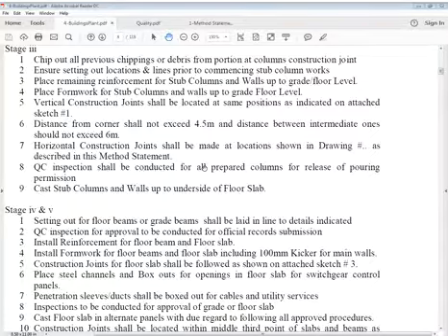When it is given on drawing, that indicates that the whole concrete cannot be done in one go because of the size and thickness of the member, and we have to provide some gap, or there is some technical requirement. Otherwise there is some failure of the batching plant or some machine, and you have to stop concrete for that reason, and there's no other way out. You can't arrange to continue, which is called an emergency case.